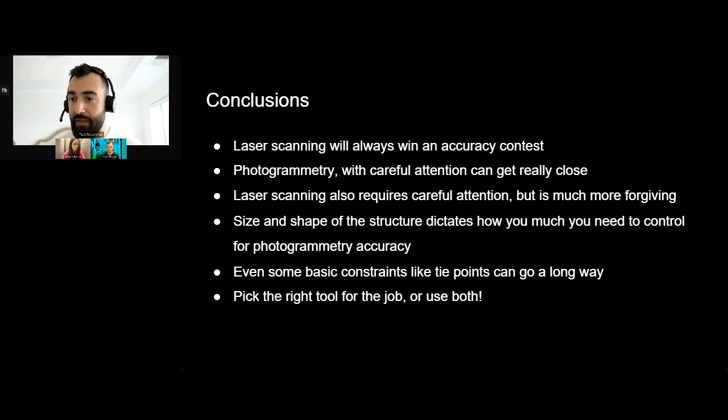Both those types, aerial laser scanning and mobile laser scanning, it's not going to give you the millimeter accuracy that you're getting from terrestrial laser scans. But again, I'm thinking you probably don't need millimeter accuracy on a coastline survey like that.